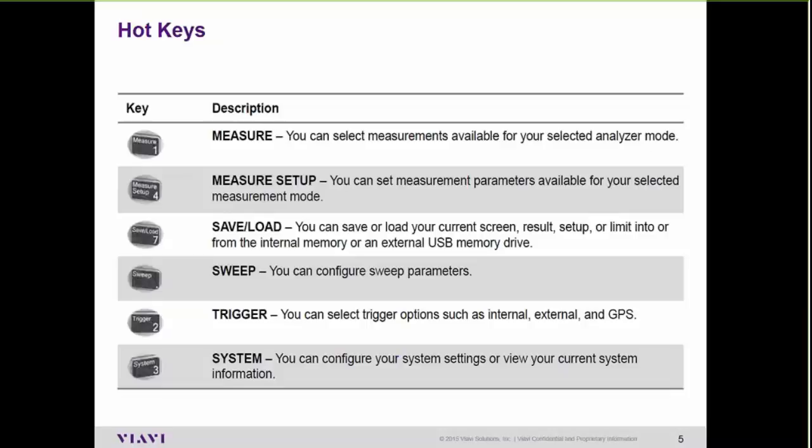Same way for the signal analyzer. If you go into the signal analyzer and select the LTE technology, there's a large group of measurements that you can run under the LTE signal analyzer. There's everything from modulation analysis, power versus time. There's some auto measure capability. There's over-the-air measurements, carrier aggregation, RAN performance. There's a whole group that you can run.